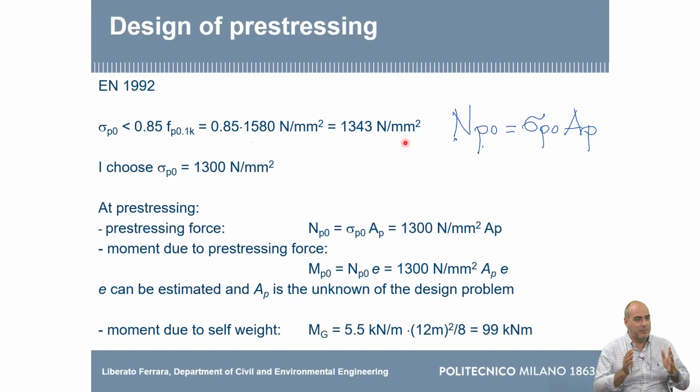When you prescribe, for example, the stirrup spacing, use 10 centimeters, 20, 25. Sometimes you just use 12.5, but you know why? Because this size here is about 25 to 30 centimeters. So generally, if you go there and inspect on the site, the workmen sometimes do this and check that they have one stirrup here, one here, and one in the middle. So consider also that these are sometimes the way in which you have a survey of your site. Okay. We speak about digitalization, but we have also to cope with the fact that sometimes most of the things are still done in a craftsmanship way.